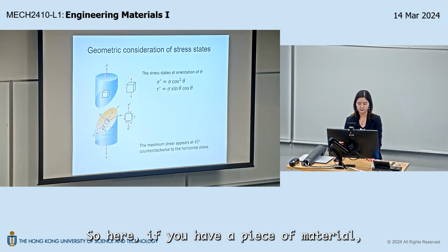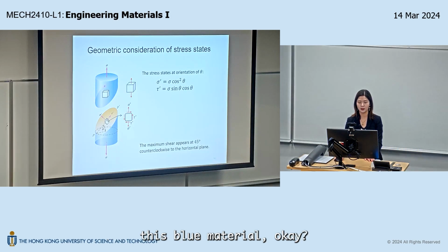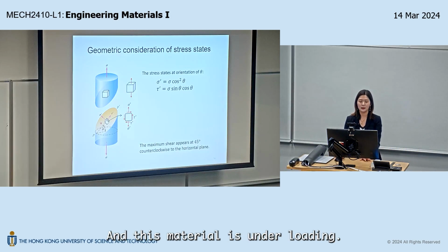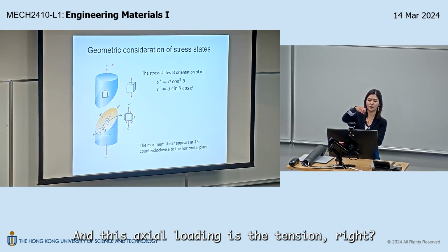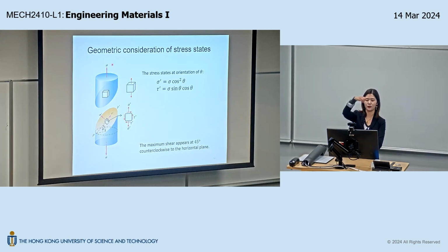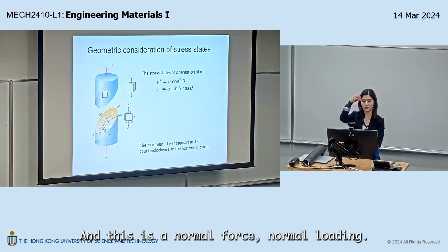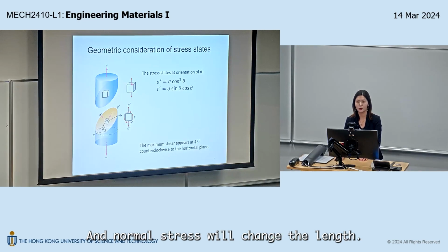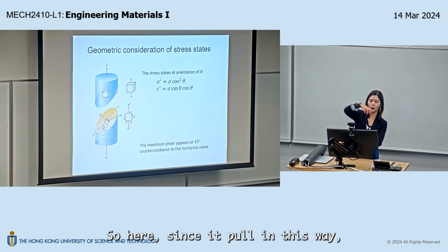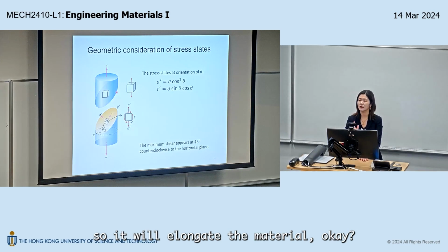So here, if you have a piece of material, this blue material, a solid material, and this material is under axial loading, and this axial loading is tension. Last time we discussed, this is a normal force, normal loading, and normal force gives you normal stress, and normal stress will change the length. Since it pulls this way, it will elongate the material.